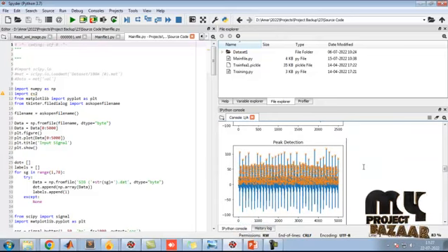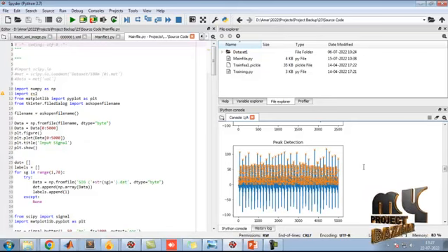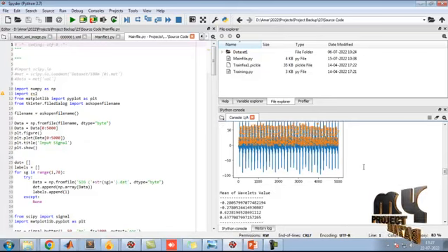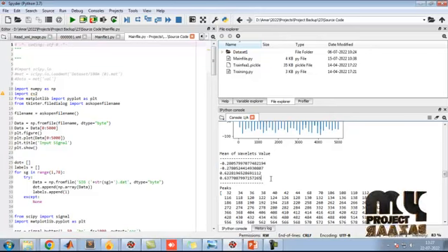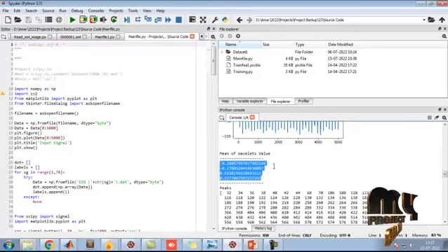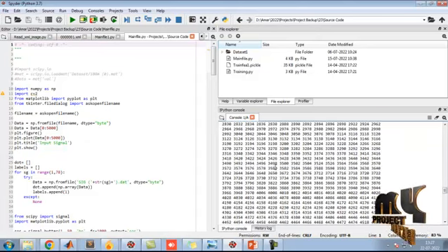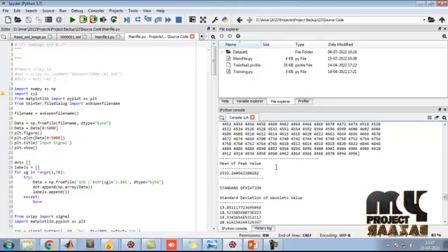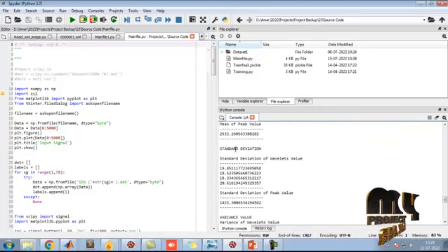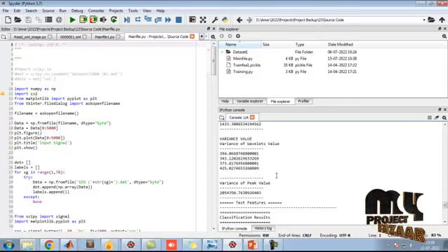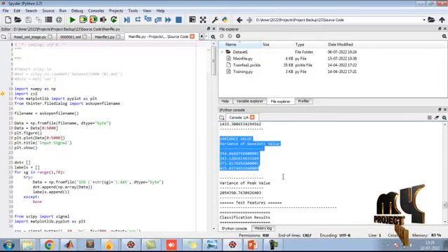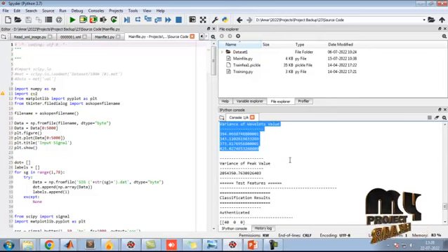So this is the figure which represents the peak ranges. After extracting the peak ranges, we extract the mean, standard deviation and variance, which are the local features. These local features are taken from the wavelet signal. After extracting everything, the values will be generated like this, that is the test feature. This is the standard deviation values, and this is the feature extraction values of variance. Then after extracting mean, standard deviation and variance, we move to the classification step.